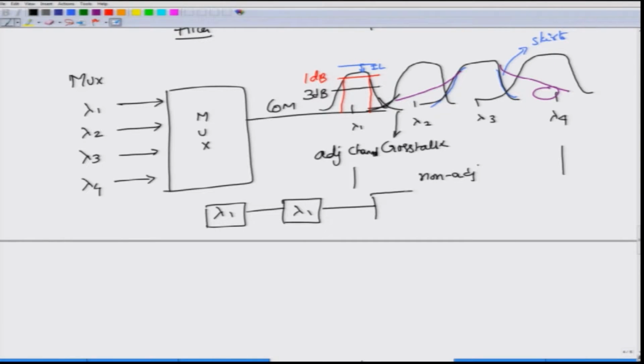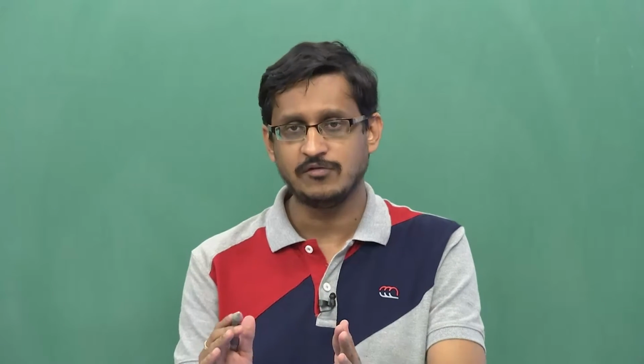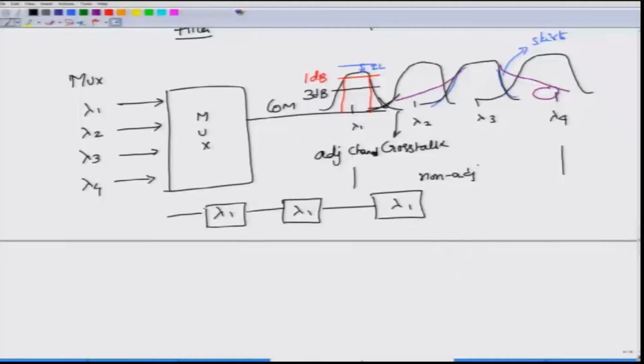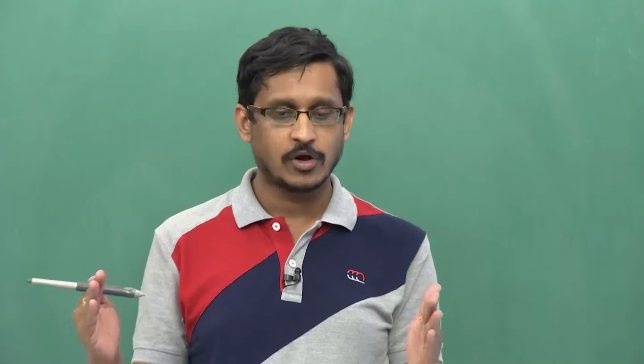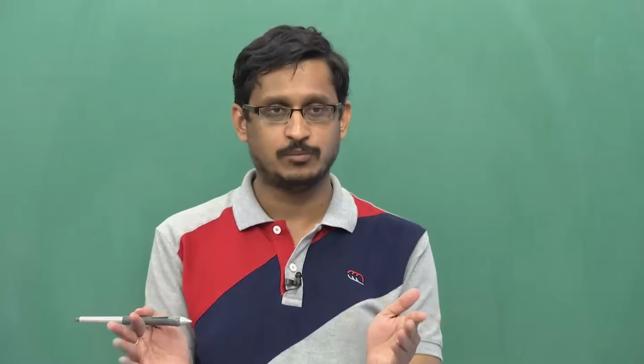them, as and when something that happens when you are looking at a long distance transmission, at each span just before the inline optical amplifier you will put an optical filter in order to limit the amount of noise entering into that particular wavelength. So, overall if you see over say 10 or 20 spans of propagation, there are about 20 filters, and if you now look at the overall response of the filters, the overall response would have narrowed down. So, it might actually cut down some of the input signal spectrum.